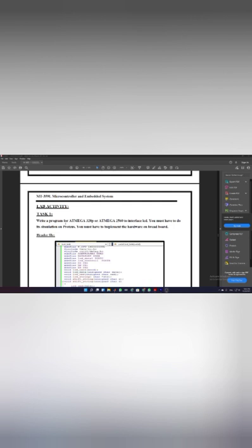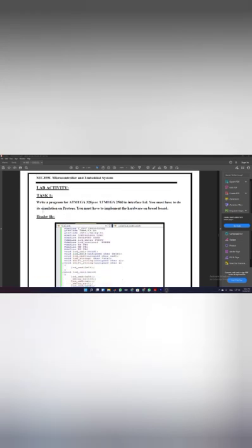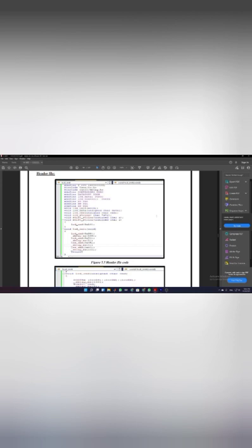This is task 1, in which we have to interface the LCD and perform the simulation just as in the previous ones. You can see that we have included the standard libraries and the CPU speed definition, and then we define RS equals PB0, RW for read/write, and enable.